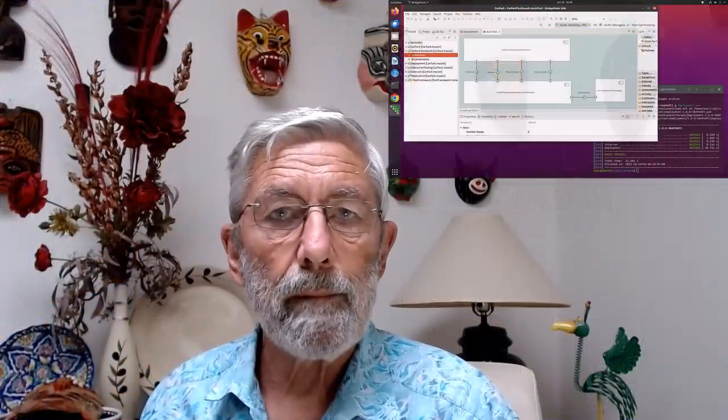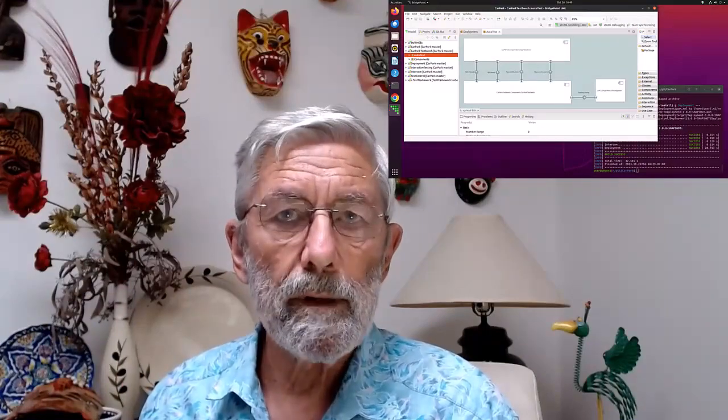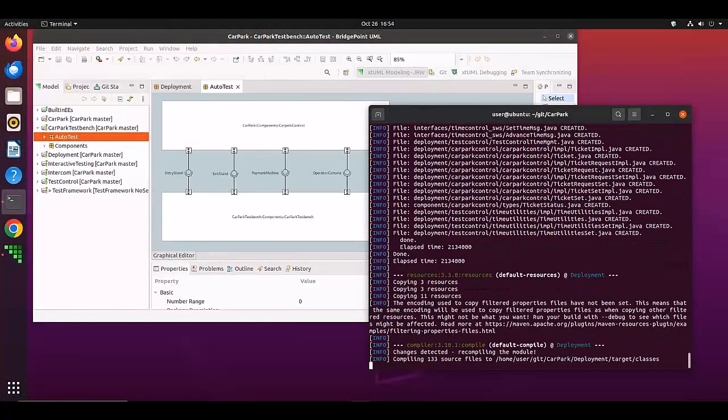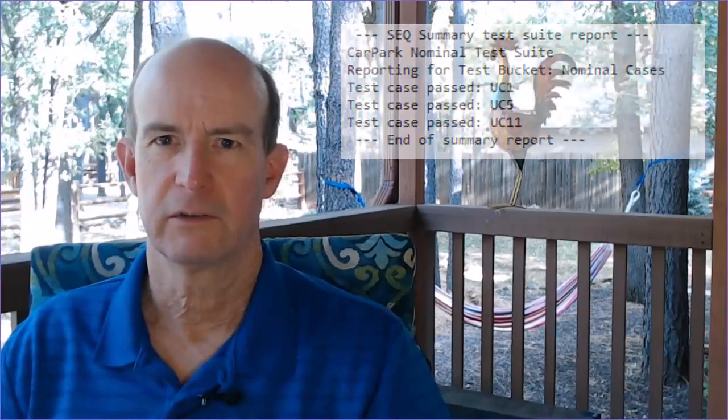Another common testing platform is the development host. Once the models are running correctly in Verifier, generating code to run on the host is a good next step. You can focus on sorting out toolchain issues while running a known test suite against application models that have already been debugged in Verifier. This is often a more convenient environment to integrate code generated from your models with external code. And unlike an interpreter, execution speed in this environment is likely to be much closer to that of the target deployment. In addition to running in multiple environments, we want each test to be repeatable so that we can track development progress and detect regression failures.